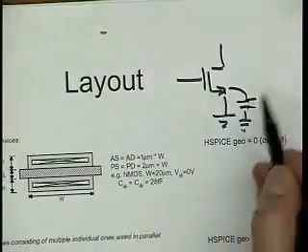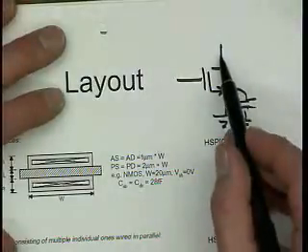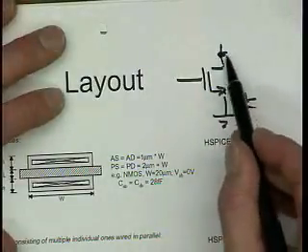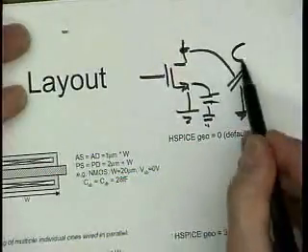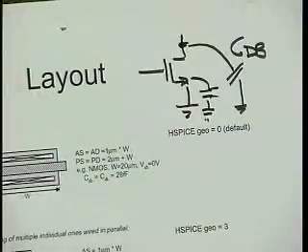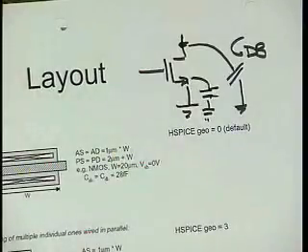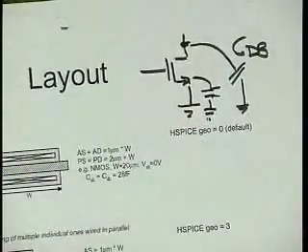So we really don't care about the value of CSB in this configuration, at least. It would be different in a cascode. Here we have the CDB. Well, that just loads the output of our stage, right? We built this big amplifier, but now it puts its own load capacitance there to slow itself down. That's not a good deal, right? So we really want to make this small.